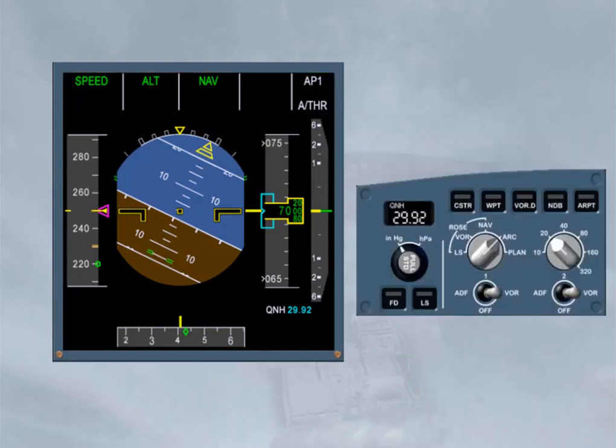A Flight Director, FD, push button on the EIS control panel enables the pilots to switch the Flight Director display on. Notice that there is an indication on the FMA when the FDs are switched on. Caution: both FDs must be switched on or both off. You should never fly with only one Flight Director selected on.